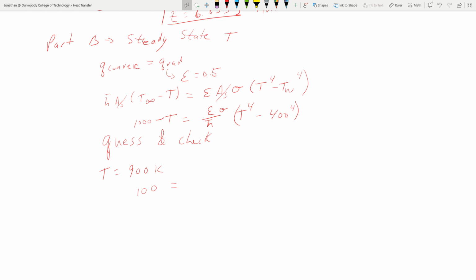I screwed that up. Alright, so 900 to the fourth minus 400 to the fourth times 0.5 times 5.67e-8 divided by 328. I got 54.49. So I think I need to be a little hotter than that.